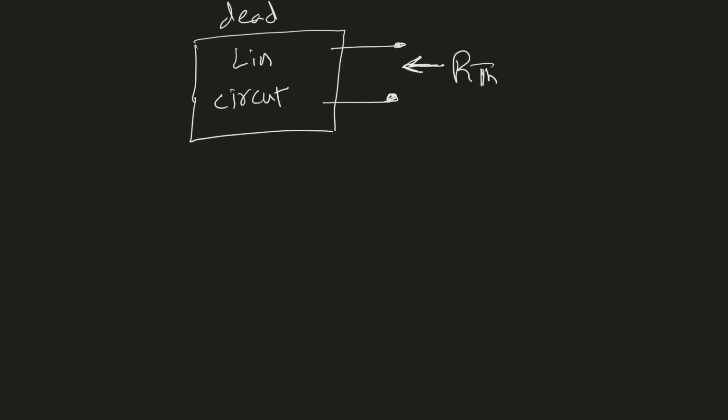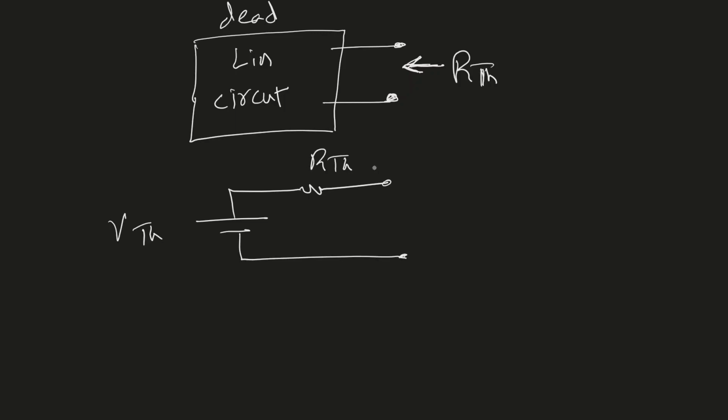Once we calculate both of these values, we will construct our Thevenin equivalent circuit, which will be represented like this. We will have VTH and RTH. These are the 2 terminals, A and B. So this will represent a very complex circuit in a very simple way. Then we can connect different loads to this, and we do not need to resolve the entire complex circuit again and again. We just need to solve a very simple voltage divider. So let's see an example to explain this method.